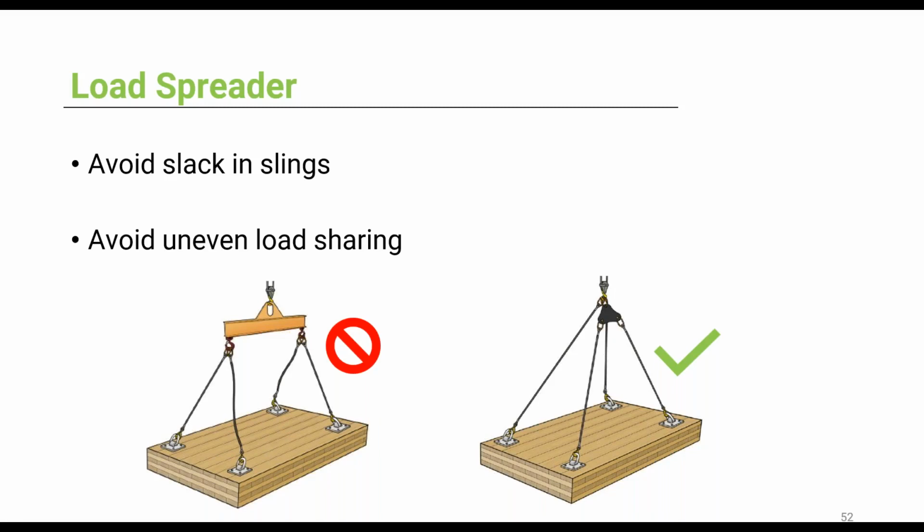Even if one of the legs is uneven, the whole table will rock. It may find equilibrium on 3 legs, but as soon as there's a movement or a load, it'll start rocking on one side and only 2 legs will support the weight. It might not seem like a big deal for a table, but when you're lifting a heavy mass timber element,